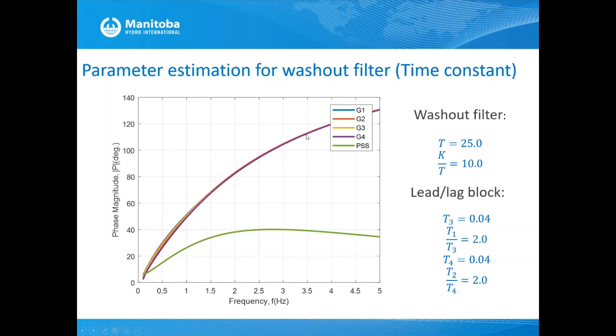So this is the lagging characteristic, and this is the characteristic of the entire PSS, which we know is a leading phase. So really, if you fully compensate, they should cancel out. But as I said, we keep a margin, and you can see throughout this range we keep a margin. So we undercompensate to keep sufficient synchronous torque.